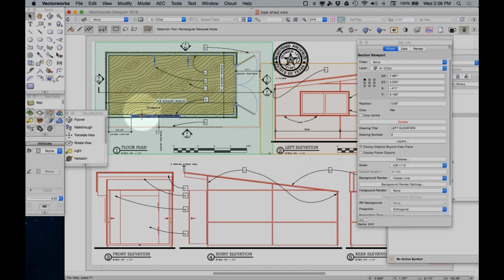If you wanted a very detailed profile, like an ogee, you're probably best to model that as a square approximation in early design, and then in final design do an extrude along path to mimic that.